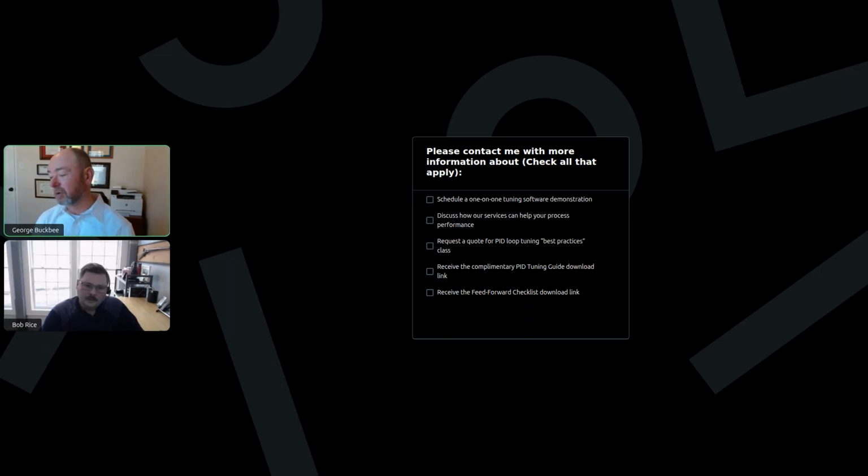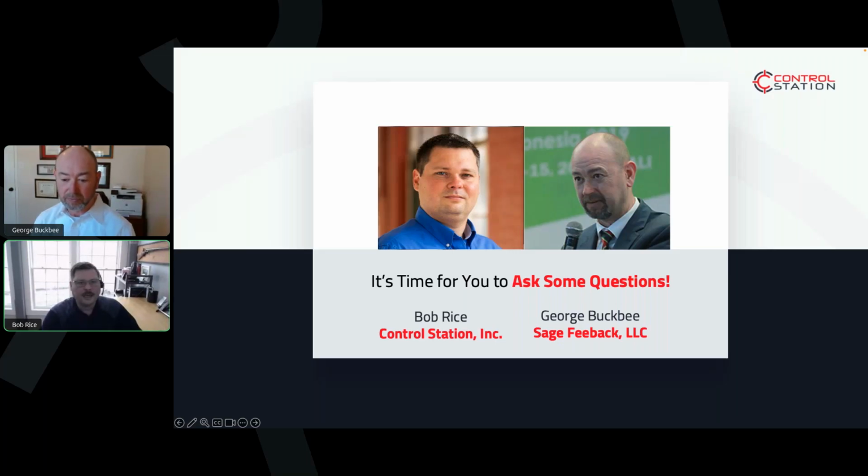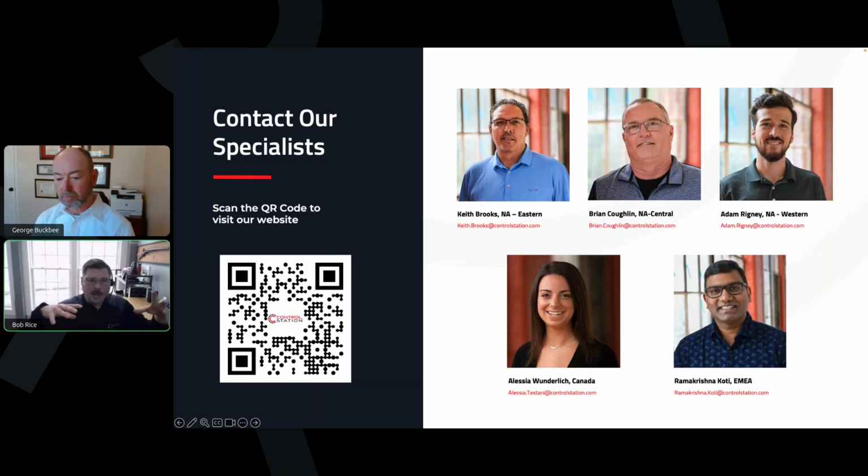Yeah, this is a question of going back and taking a look at the model, the disturbance model first, is where I would start and ask, do we have an accurate disturbance model here? Or is the feedback hiding the fact that our feed-forward model might be wrong? Yeah, and sometimes looking back at the dynamics that occur when the operator takes it to manual control may change how the feed forward actually needs to compensate, because maybe there's less impact or something like that. So depending on how it's implemented, for sure.